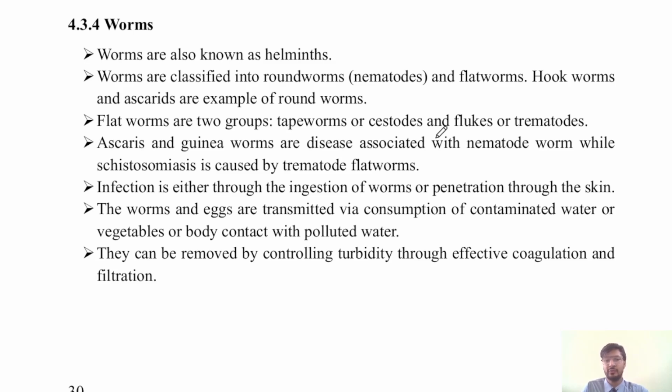Infection is either through the ingestion of worms or penetration through the skin. The worms and eggs are transmitted via consumption of contaminated water or vegetables or body contact with polluted water. They can be removed by controlling turbidity through effective coagulation and filtration.